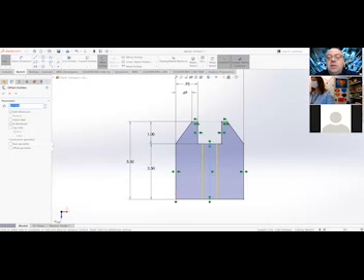So when we look at something and we can make a better decision about it as we make our designs, then we're more likely to get a successful result. So this is where I want it. We're going to do 0.3125, which is 5/16, bidirectional. We're doing one line, so that's why you do not have the chain, and then select the green check mark.